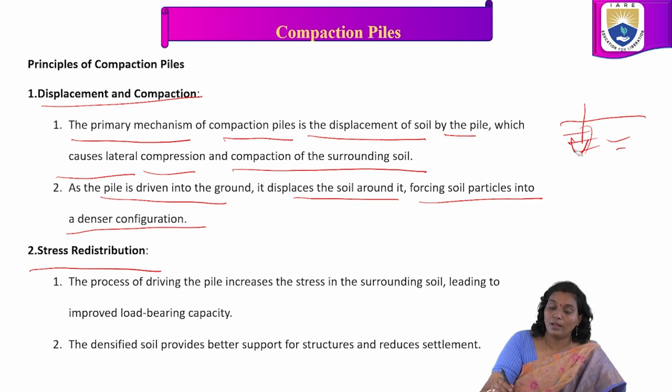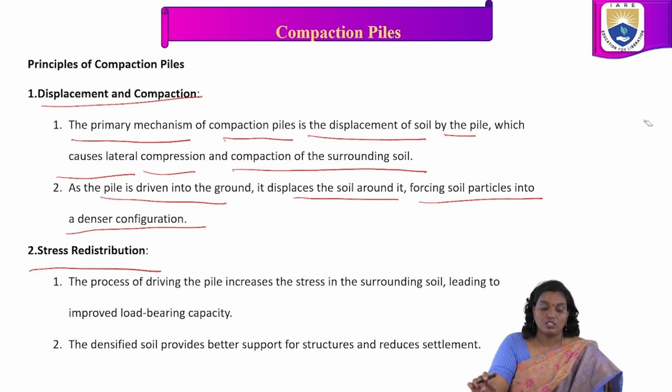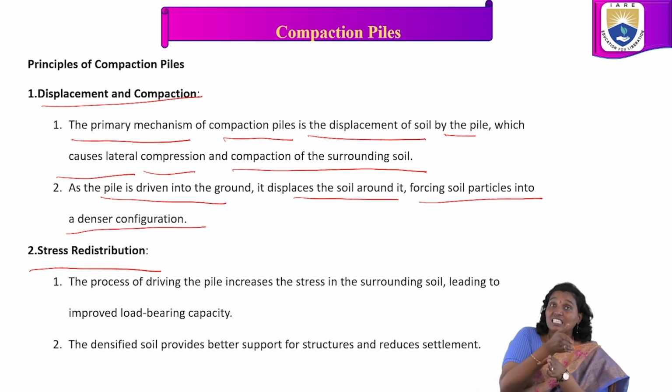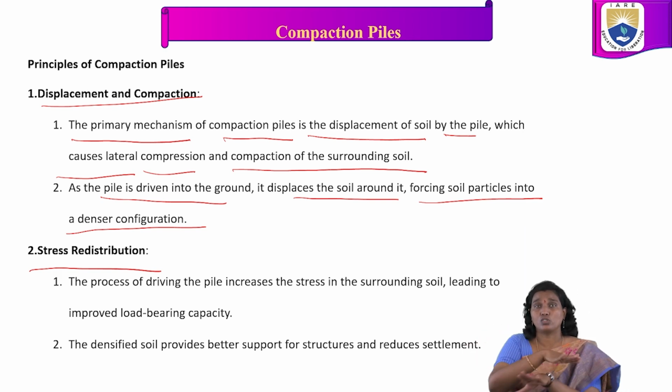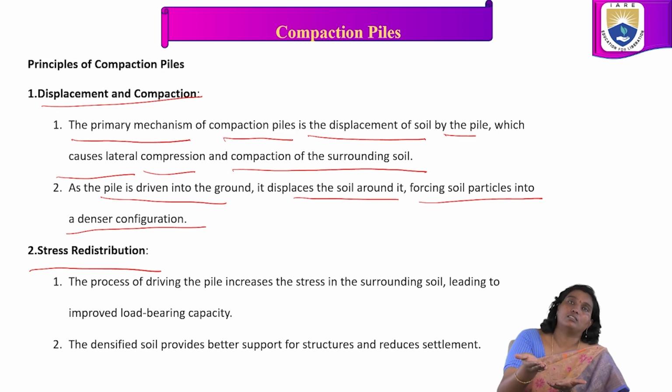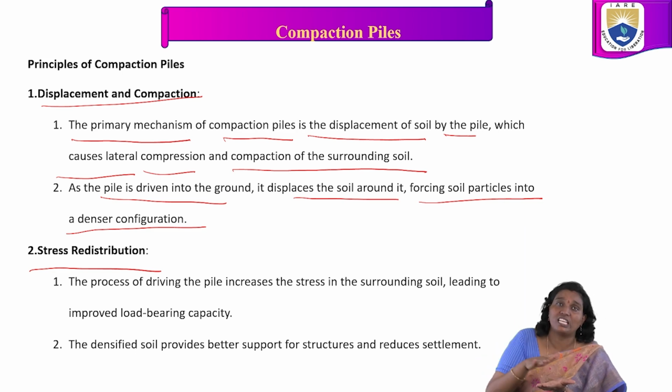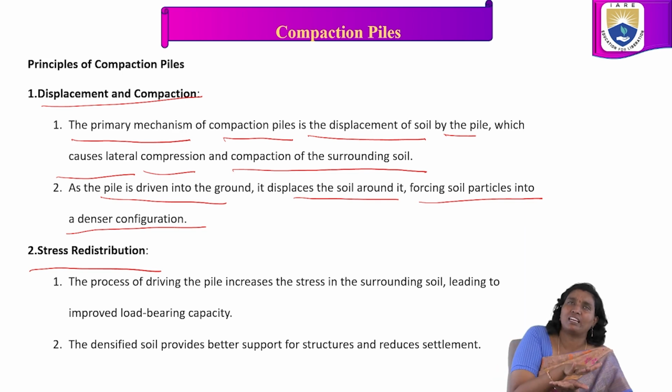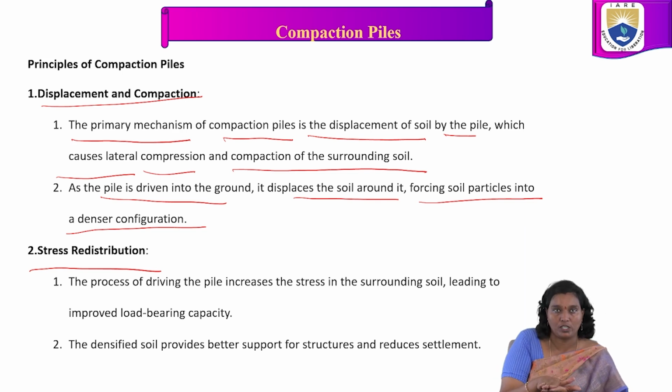It depends upon the surrounding soil. The pile increases the stress in the surrounding soil, and that stress is going to distribute. But it is not the same as the previous status of the soil before inserting the pile. After inserting the pile, the stress distribution is different. This is nothing but stress redistribution.